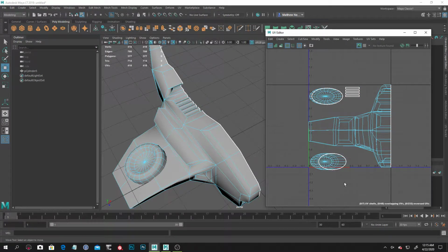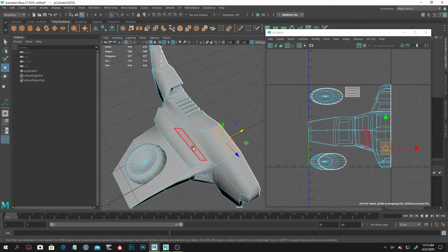So I've got the main model, I've got those little grill pieces, and I've got my two little cylinders right here. So what UVing is, we've taken a picture of our model, but now we need to make cuts to flatten out these pieces. These are kind of coordinates for where our textures are going to be projected onto the model. So when we start painting this model in textures, all these polys, all these positions, right? They need to know what they're looking at in terms of what is called our UV space, which is this little square right here, right? So we need to make what are called shells that are positioned in this space that'll project whatever texture we eventually paint onto these specific models. But they have to be flat in order to do that. They can't be like a big contour shape like this, right?